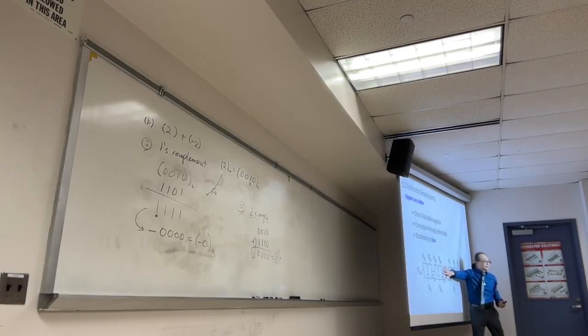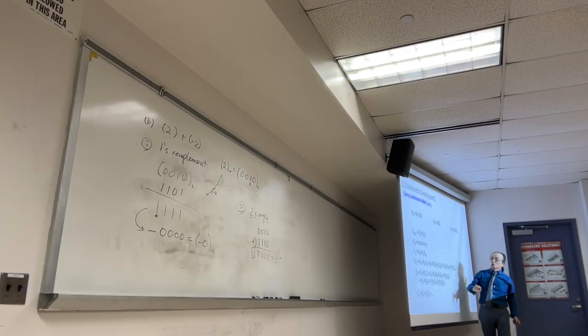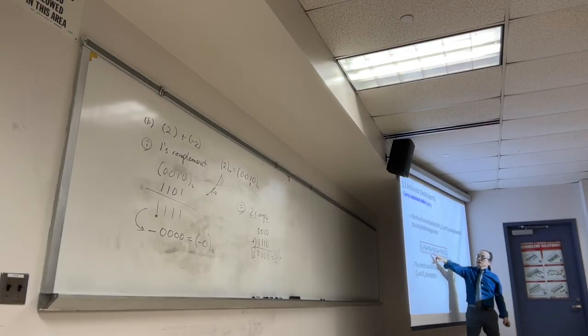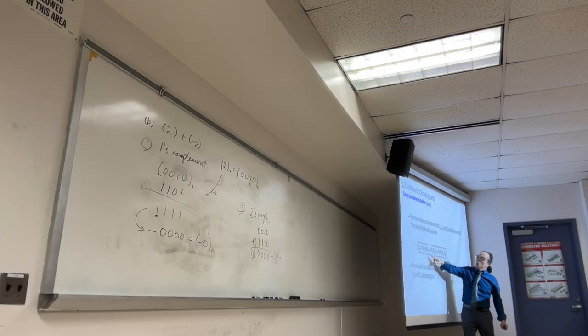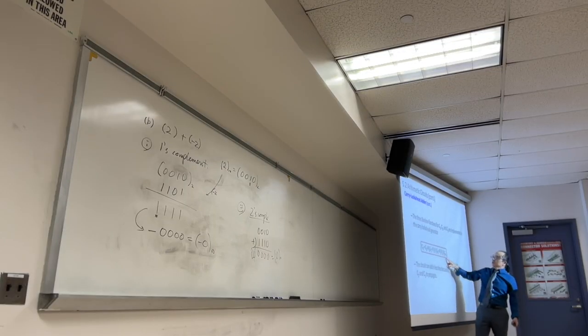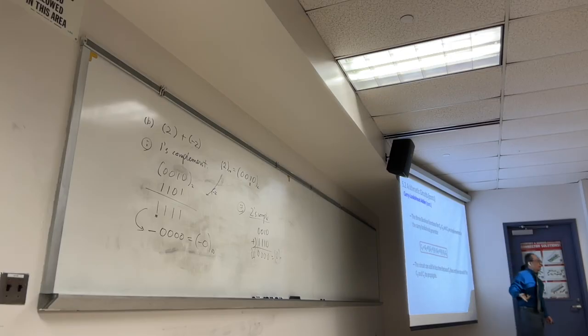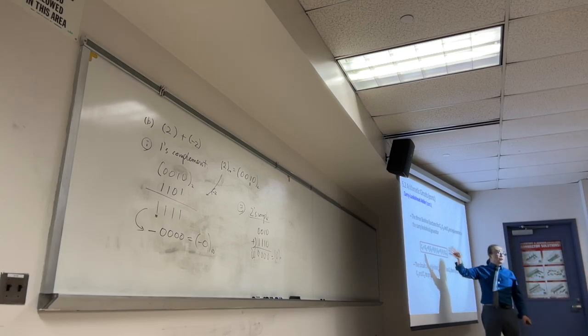In that equation, if you see it, for carry bit 3 here, we don't have to know carry bit 1 or 2, only carry 0. Based on this circuit, if we know the first carry, if you keep expanding this equation, then we don't have to wait until C1, C2, C3, C4, all the way to C32.